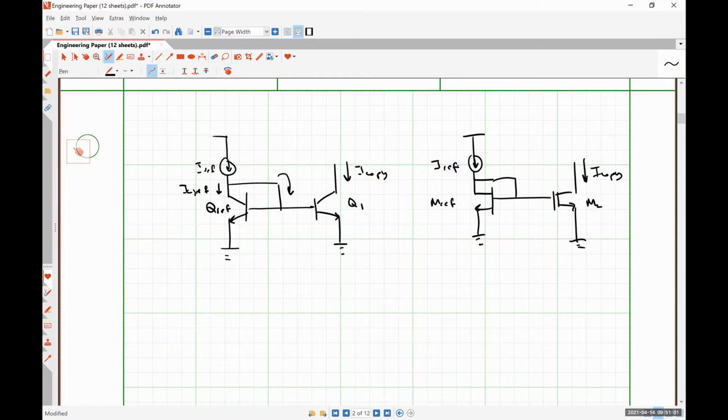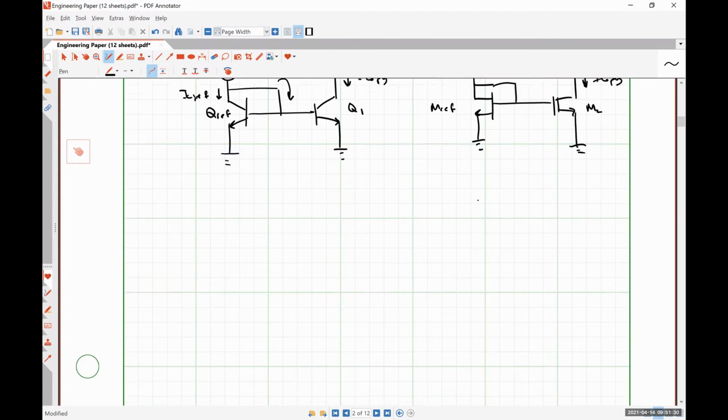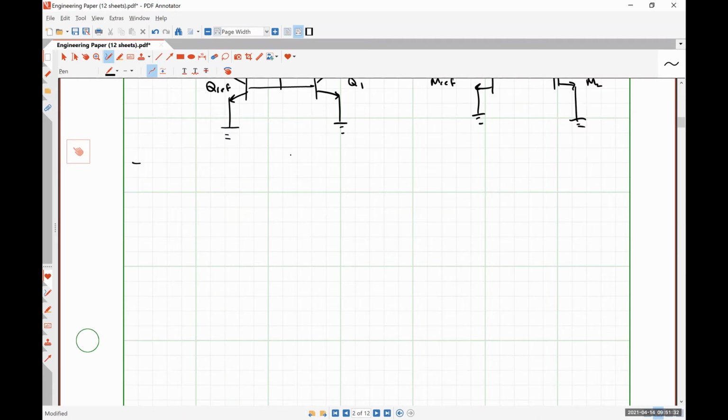So circling back around to current mirrors here. The current flowing through this branch has to be 0 because there's no current flowing into MREF, and no current flowing into the gate of M2. So IDREF is exactly equal to IREF, which is exactly equal to ICOPY. Could you give us a version of that example, assuming that there is base current flowing? Okay, we have one at home, so that's pretty cool.